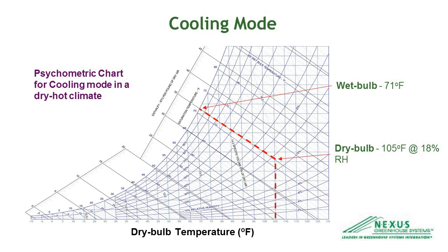Another way to look at that is by using a psychrometric chart, which we show here in this diagram. The bottom axis, the x-axis, represents your dry bulb temperature, as Dave said, the temperature that your thermometer reads. The curved axis on the top of the chart represents the dew point, or where the relative humidity reaches 100%. This is the maximum theoretical amount of cooling you can get with an evaporative process. And as we mentioned, the pad wall system achieves about 80% of that maximum.